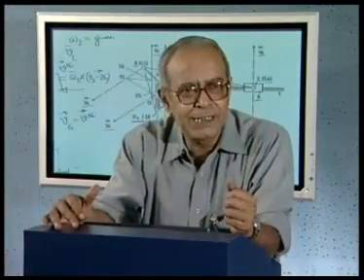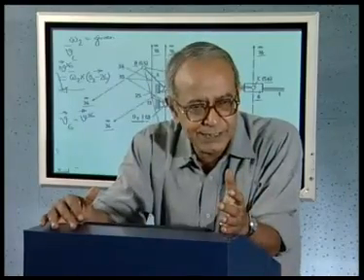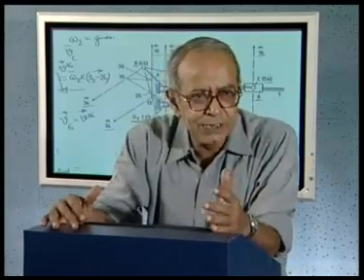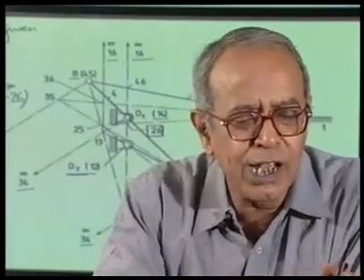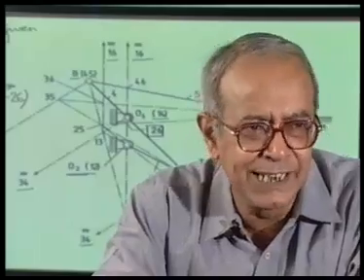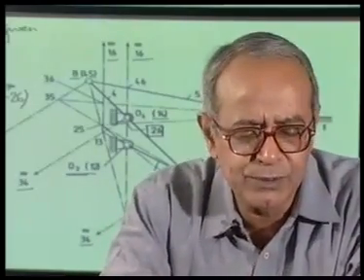So, in today's lecture, we have seen how to determine all the relative instantaneous centers of planar linkages by considering the different kinds of kinematic pairs and by successively applying the Aronhold-Kennedy theorem of 3 centers. This method is definitely going to give you a result so long as you have not more than 6 links in a mechanism, which is sufficient for the purpose of this course.